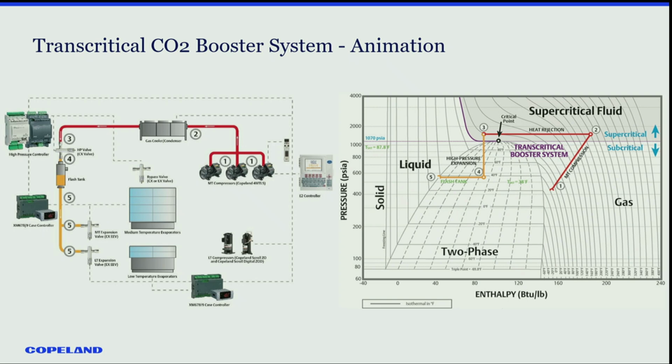And then I've got liquid in my flash tank that feeds all my expansion devices. So I've got 520 pounds here, and I've got 400 pounds here. I've got a 120-pound pressure drop across the valve. And when you're sizing these expansion valves, the head pressure is not this head pressure. When you look at a sizing chart, the inlet pressure you want is your flash tank pressure. It's a little bit different way of thinking because that is your inlet pressure. So you go through the evaporators, one mass flow going into my suction. My low temp, I've got 200-pound suction, 520 here. I've got 320-pound differential, which you've got to size that valve for that differential.